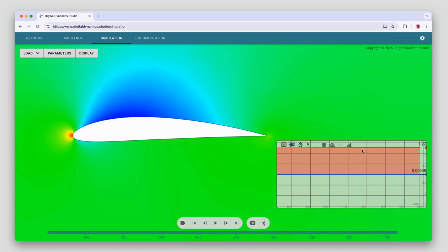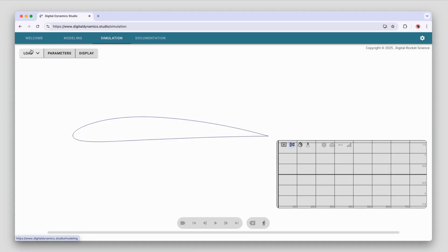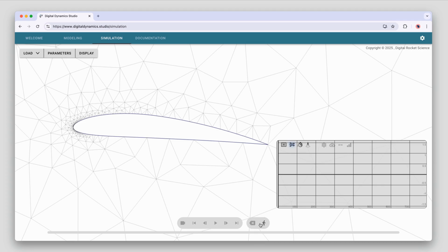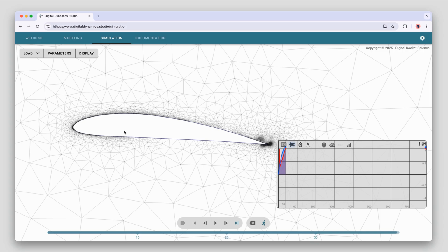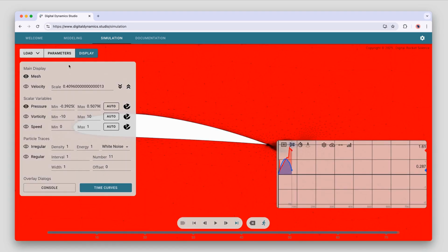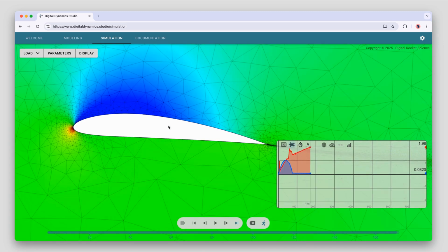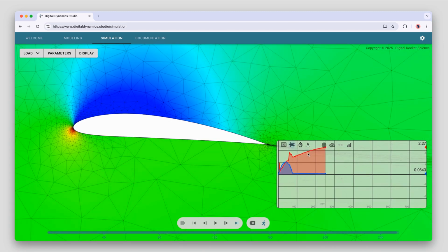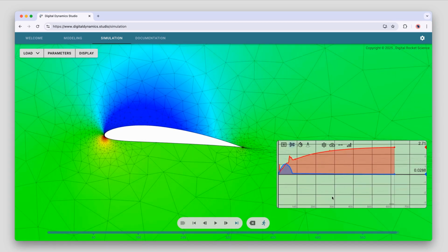So remember at 10 degrees the lift was about 4.2, and now at 0 degrees the lift is 1.27. You can try something else. Let's reset the simulation and try 5 degrees. Go back here, reload that, and push the run button again to run that simulation. And there it goes. Let that run for a while. There's always some messiness at the beginning of the simulation, but things usually dampen down after a bit. So there it goes, and let it reach a steady point.